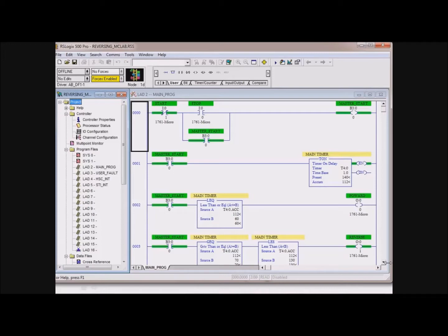So you're at a plant like US Steel and they want to fire up all those motors. When the motor pulls 100 amps when it runs, that means when you try to start it, it would try to pull from 600 to 800 amps. So a lot of times they'll stagger start motors. You hit a button and the first motor will start, and then what? After a certain amount of time, the second motor will start. After a certain amount of time, the third motor will start.